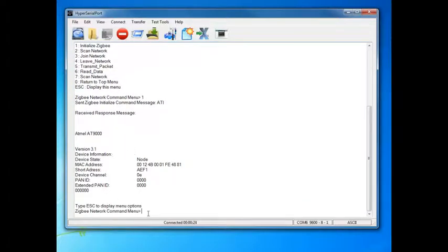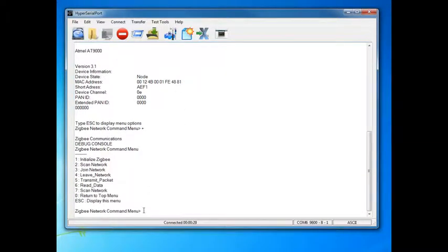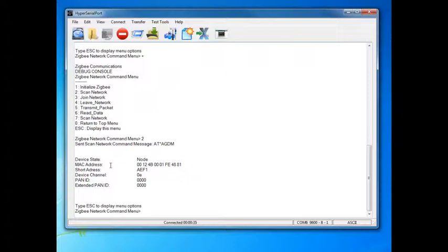Here you can see the Initialize ZigBee command that was sent to the ZigBee emulator. The MSP430 sends a command consisting of a string of hex numbers. The ZigBee emulator receives these numbers and sends back a response message consisting of a string of hex numbers. These values are then displayed in the terminal window. Choose any menu command by entering its character into hyperserial port.